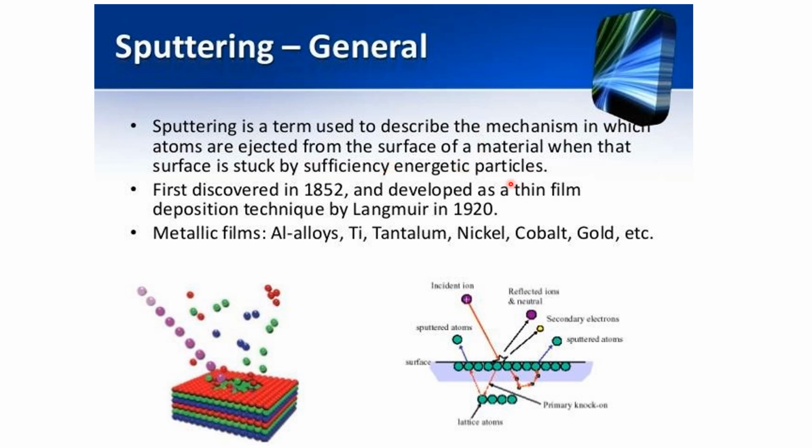Sputtering is used when high energy particles strike the target, and then we get the atoms from the target and can deposit the films. Most metallic films, like aluminum or titanium or some alloy films, can be deposited using sputtering. You can see that high energy particles are coming, and then they eject the atoms from the target, and these can be deposited on the substrate.